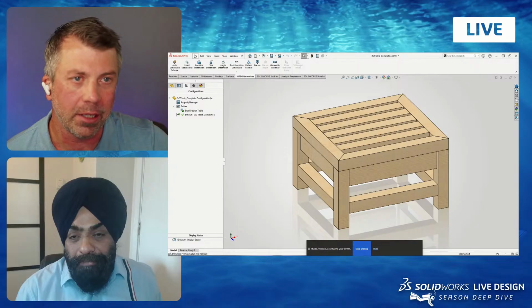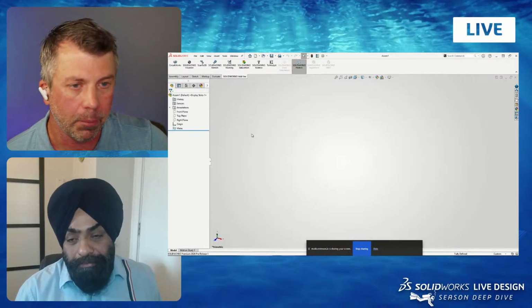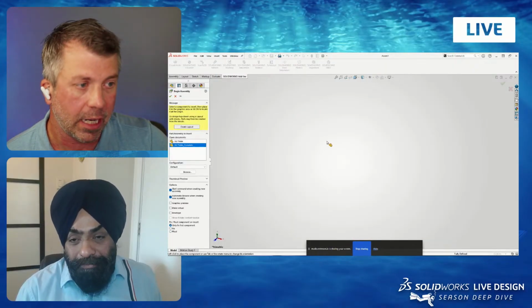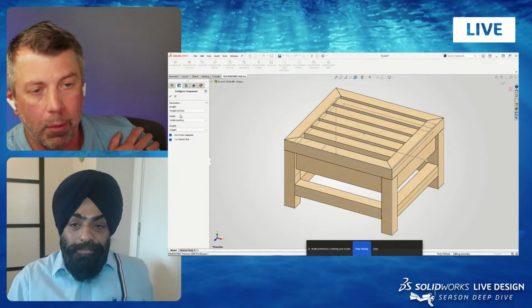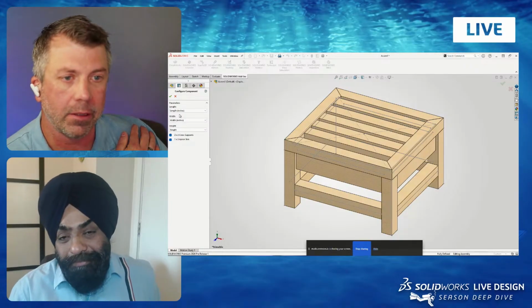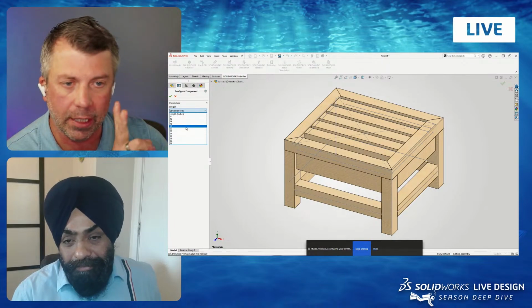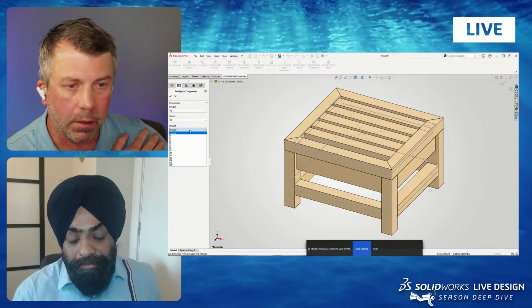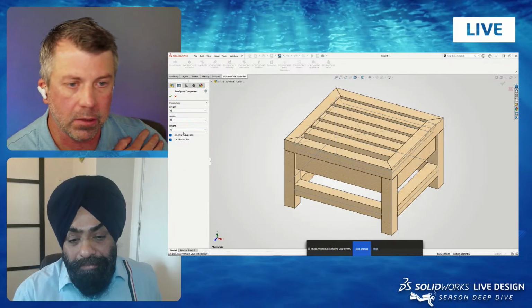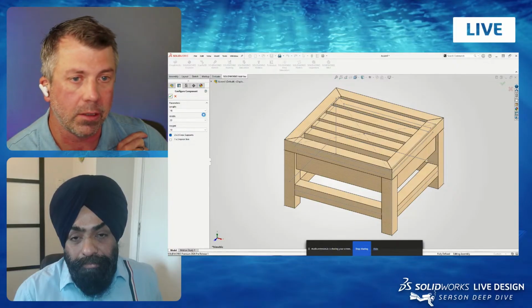That's fine. Okay, so what's the magic, right? Why is this so cool? So now if we make an assembly and we want to import our completed table, once we drop this in here on the left-hand side, you're going to see what I would have created. What I couldn't show you because it scaled off into the abyss. We have our length. I just preset these values, 10, 12, 14, again, 2-inch increments, so my pattern works nicely. The width is 22, the height's going to be, I don't know, 10 inches. And we'll say, let's just do the bottom cross support. So none of this has been created. I only had the one configuration in this model.